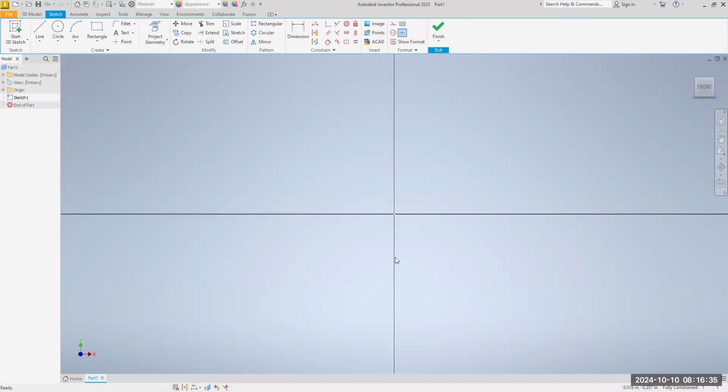All right. And as before, you can always zoom in by rotating your scroll wheel. You can hold the scroll wheel down to pan. All right. So I want to use the revolve command to make some screws today. And the first one we're going to do, if you look at the handout that I gave you, and this handout is, again, you can access in the OER13 module.